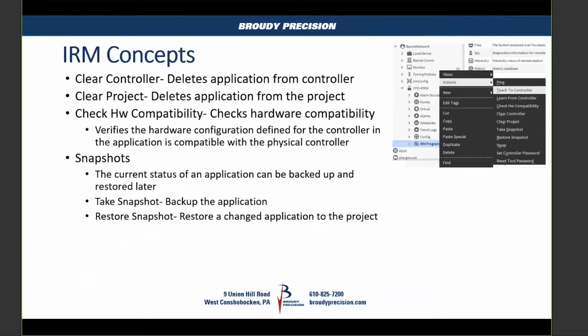Some of the other commands that are listed there, you have your clear controller. That's a way to clear out your controller, as it says, and basically deletes the application from the controller. And there's also the clear project, so you can delete the application out of your project as well. So I'd be cautious using those. There's a check hardware compatibility. So basically, it's verifying your hardware is going to match the application. Like you put the template in for the large controller, and you actually have a small controller you're working with, that kind of thing. It'll let you know if there's any problems.